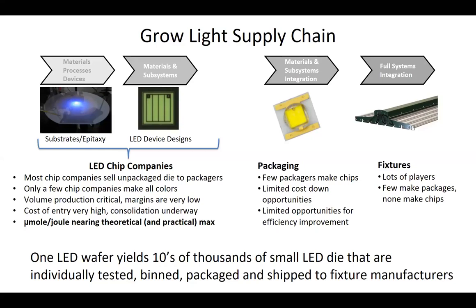Under perfect conditions, where the package is very good and the fixture is very good, the mean time before failure of the LED is that, well, actually it doesn't fail. It just gradually gets dimmer and dimmer, with a reduction in output power to, say, 70% of original value, at anywhere from 50 to 100,000 hours. The chip is really very, very reliable. Once you put it in the package, the aging can be somewhat faster, but we're talking about a gradual reduction in light output. Very, very little in the way of filamentary failure where it just blinks off. Lifetimes there are probably in the 50,000 to 75,000 hours.